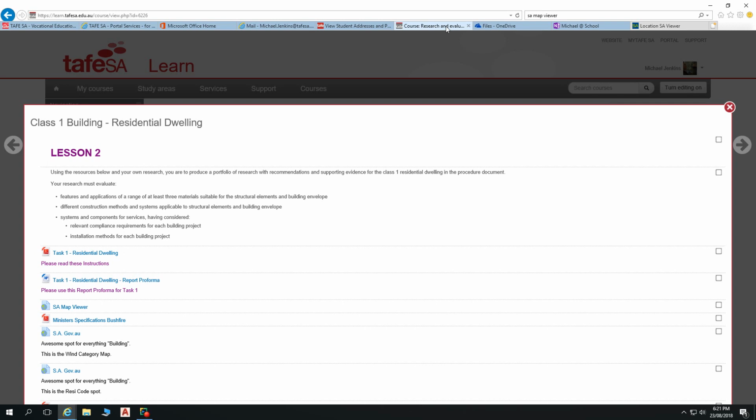Maintenance in regards to other building products. Steel: once again, steel needs to have protection against corrosion. So galvanizing typically means that the steel will last a very long time without any maintenance requirements. But if it is unpainted steel, or if it's ungalvanized and it's painted, then that needs to have paint applied regularly to keep it in good condition.